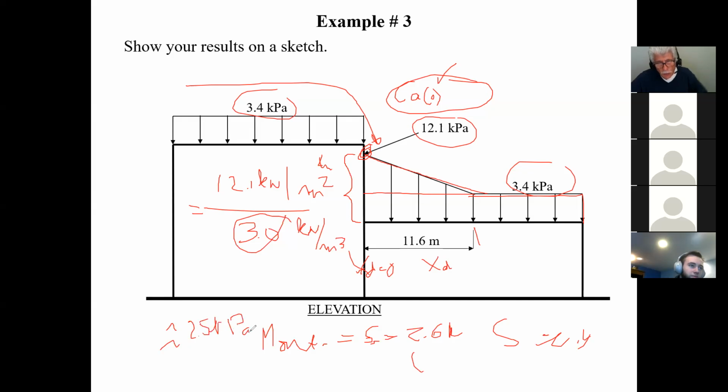That's the average snow load that the buildings are designed for. So if I take 2.5 kPa divided by 3.0, what do I get in terms of height? I have about 0.83 meters. You guys agree?